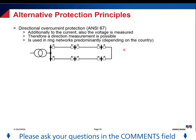So how do we cope with this problem? Well, the first alternative to this is directional overcurrent protection. So additionally to the current measurement with the CT, you also measure the voltages with a voltage transformer or a potential transformer. And based on the angle between voltage and current, the protection device can decide where the direction of the fault current is. So in which direction does the current flow.